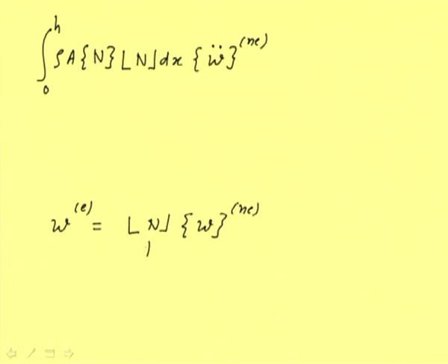So this is a function of x and this is a function of time. So the time derivative is taken by the w Ne, and this is inside, because now this is not a function of x, so it can be taken out. Similar terms are there for the inertia, or similar terms are there for the elastic force, elastic term. Here N has a double derivative.